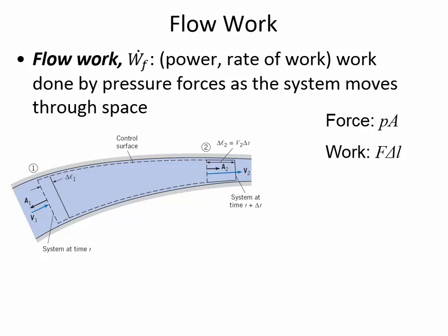All right, so water that flows through a pipe is doing work. And the reason for that, remember that force is pressure times area. Well, if we cut a pipe with our control surface, which is a technique from analysis, drawing an imaginary line around something and analyzing what's happening on the inside, what's happening on the outside. If we cut a pipe with an imaginary line, then there's pressure on either side of that pipe. And so the water that's on the outside of the control surface is pushing towards the water on the inside. And so a pressure acting over an area is a force. And you accounted for that in momentum.